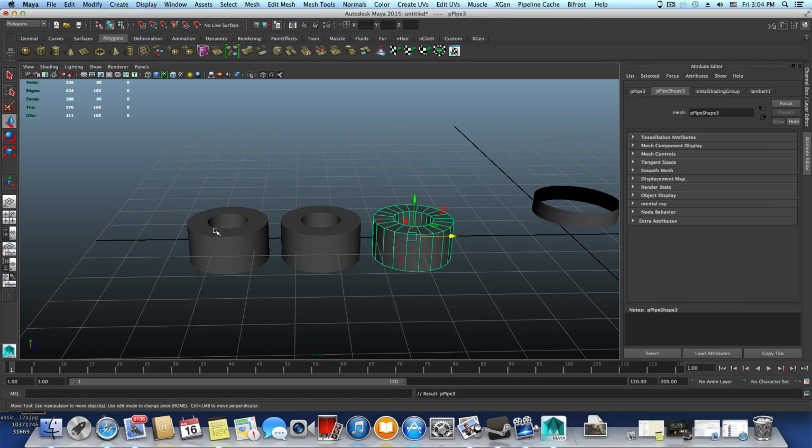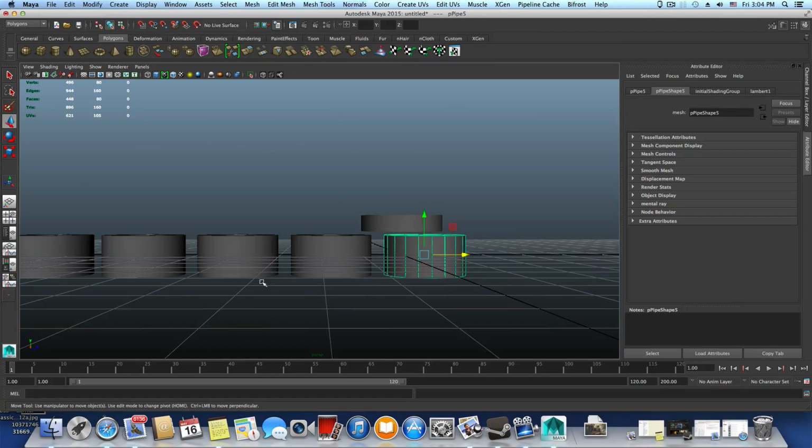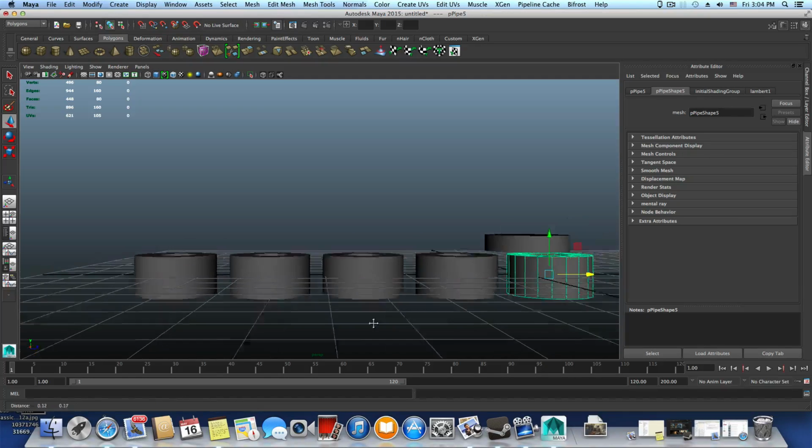from this point over here. Okay, so the third copy that you created by tapping Shift D will be following the same pattern. So I can continue to click Shift D and it will simply create copies with the same distance in between them as the first one, between the first two.